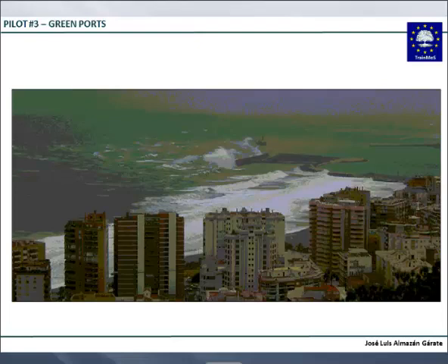Now the old dike, first of all, creates the sheltered waters of the port of Malaga, separated from non-sheltered water. But it interferes with the movements of sand, because the ports are making the coastline, and the coastline has sand movement. Now, that sand is stopped by the dike, and the sand stopped by the dike creates an artificial submerged beach.